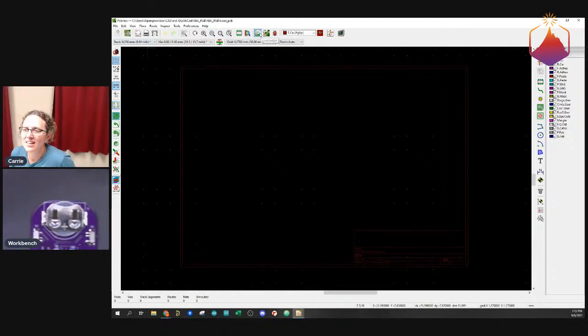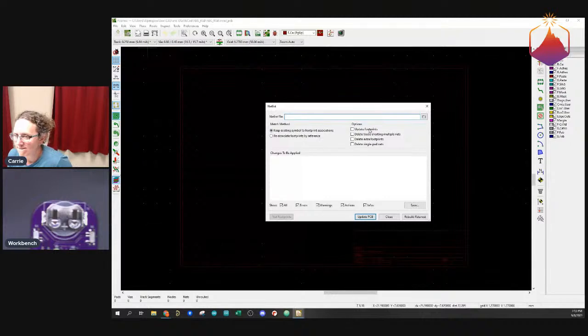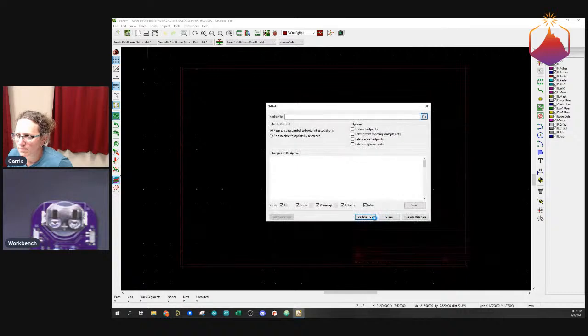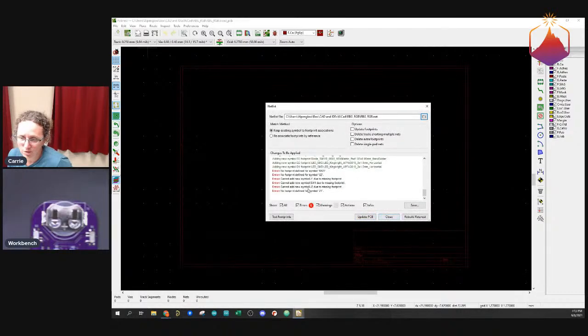So, all right, let's load a netlist. Netlist file. How about the one we just created? Okay, so a few errors that no footprints were defined. That's fine. I'm okay going forth with that. We know about that. There are a bunch of options here, and you might go back and forth between schematic a few times during the course of a layout, like we undoubtedly will when we make those other footprints.